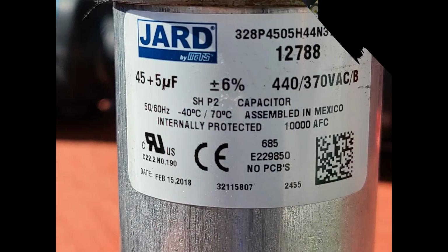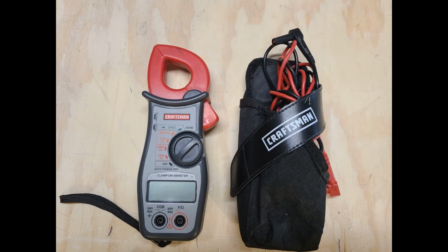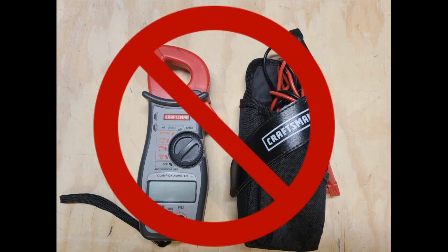It's possible to test your capacitor if you have a multimeter with a capacitance capability. I have a good meter, but it doesn't measure capacitance. I've seen meters with capacitance capabilities for sale in the $60 to $80 range. However, in this case, when neither the fan motor nor the motor compressor starts, and you can hear them trying to start with a humming sound, you can be fairly sure that the problem is a $20 capacitor. Consequently, I have opted not to buy an $80 multimeter to fix a $20 problem.